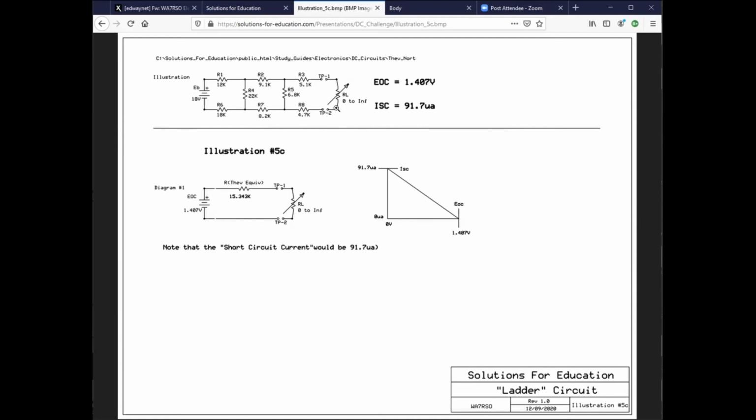Now, that is called a Norton's equivalent circuit, not Thevenin's. Thevenin's is open circuit voltage. Norton's is short circuit current. And you say, wait a minute. I get the short circuit current with my Thevenin's. You see that? I can get the short circuit current using my Thevenin's analysis. There it is, right there, plain as day. Oh, yeah, okay. What about the circuit you told me about?